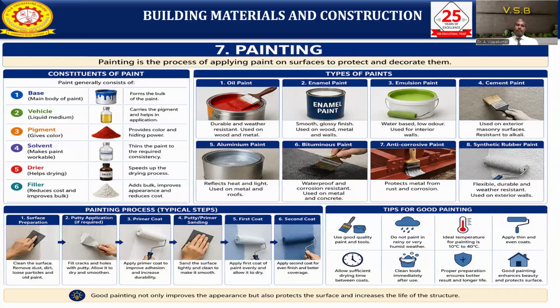So we use putty. To the putty we add a small quantity of water, then it will be hydrated and make a paste. Using this putty paste, we fill whatever holes, small cracks and defects are there in the structure. Everything we need to fill up using the putty.